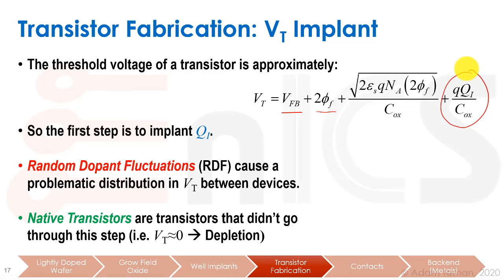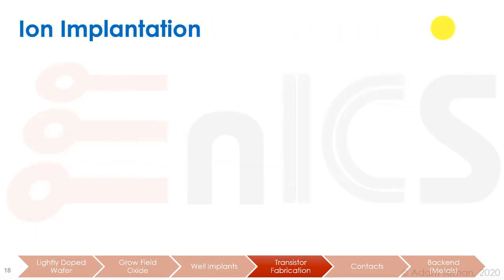There's another point where we can implant the transistor in such a way that we bring the threshold voltage to about 0. These are called native transistors. You may see them in different process design kits. It's similar to what used to be called a depletion transistor, which means it's an always-on transistor. To turn it off, you have to use a negative VT, but it's mainly used in analog circuits where you want to remove the VT drop over an NMOS. They are not a standard transistor, and therefore they require larger DRCs. You need bigger spacing around them, but they do exist in many design kits.